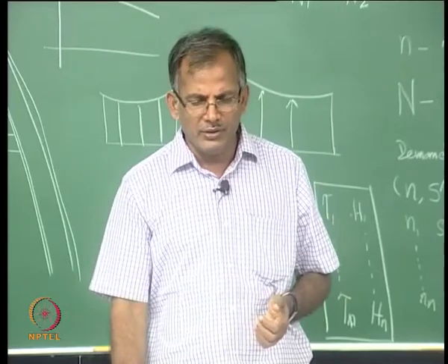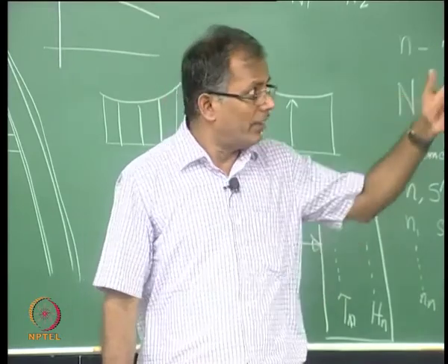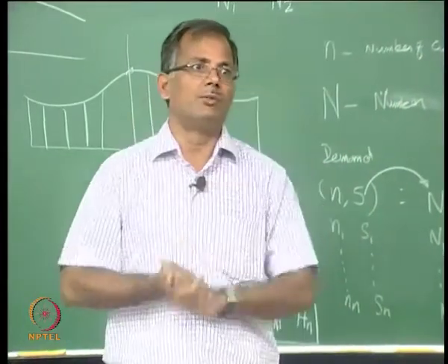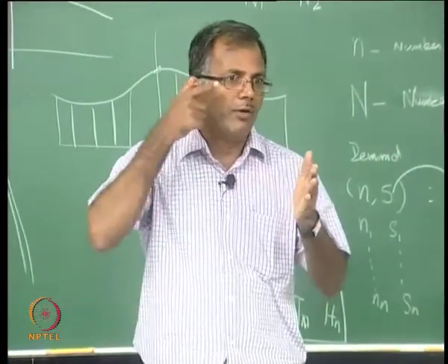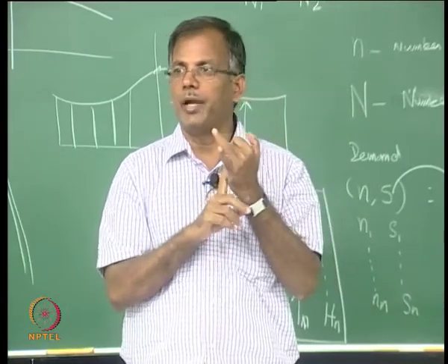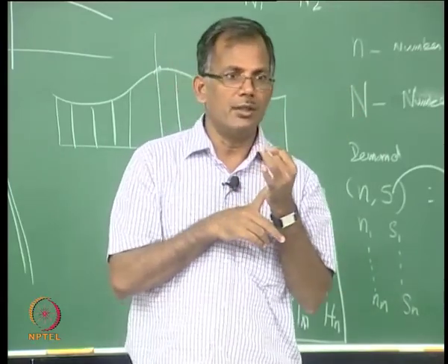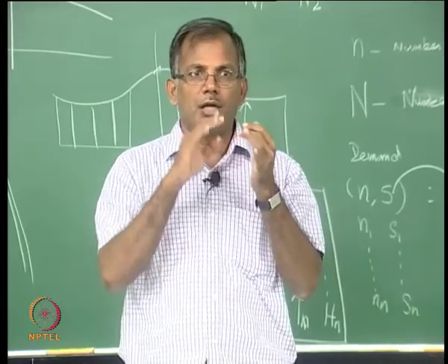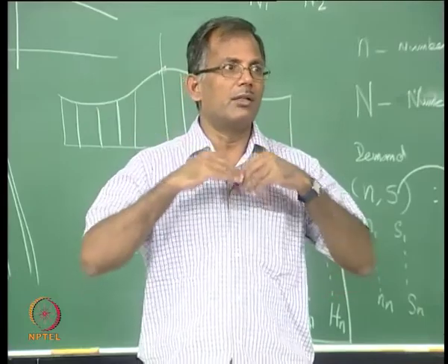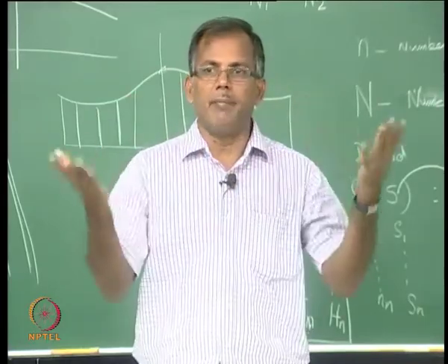The reason we need inspection is that fatigue damage is cumulative. For example, if you go for a 5-year plan, every 5 years we will go down and look at the joint for any crack, propagation or initiation. Remember the threshold: until the threshold is reached, the joint is not going to show any failure. Only when the threshold is reached does it start opening up and you can see it.